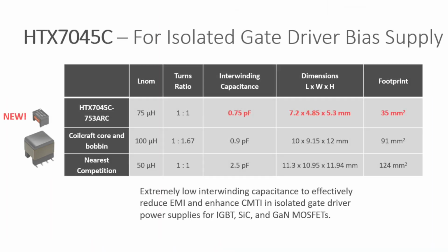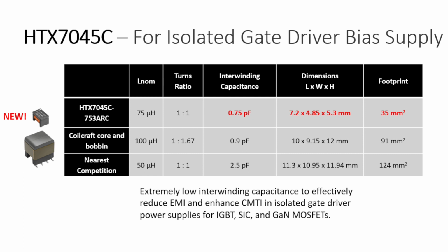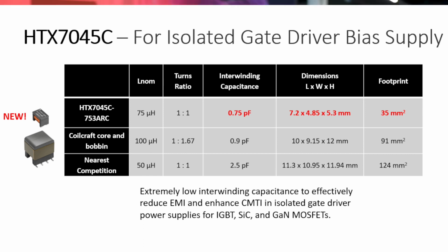And depending on how you optimize that converter, what type of circuits you use, the parameters within the inductors might change. For example, we're seeing a lot of specifications to define the capacitance between primary and secondary, the interwinding capacitance, which for many years was just sort of secondary to the inductance and the leakage inductance. And very much the right performance depends on the circuit and how we balance those.